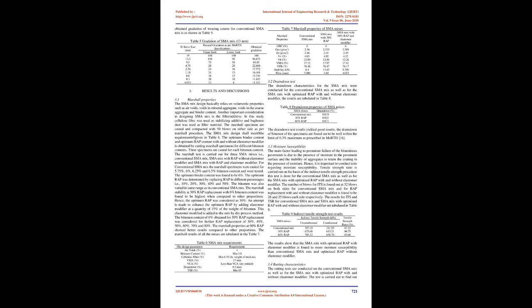2.5 Gradation of aggregates. After the basic tests, the aggregates are further used in the determination of the proper blend to give a good mix consisting of different aggregate sizes. The different sizes of aggregates used to obtain the proper blend are 20 mm downsize, 12 mm downsize, and 6 mm downsize and stone dust. 4,000 gm of aggregates were taken for sieve